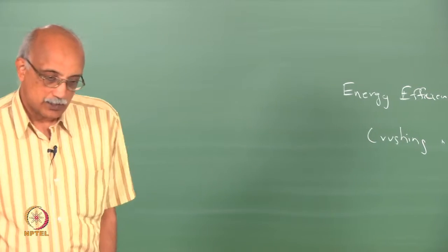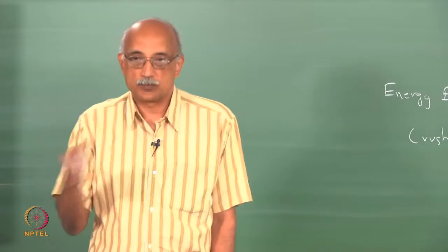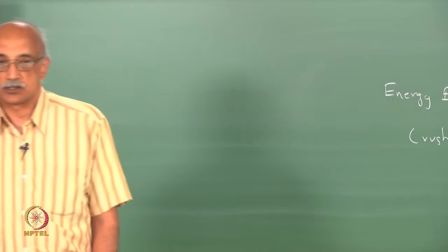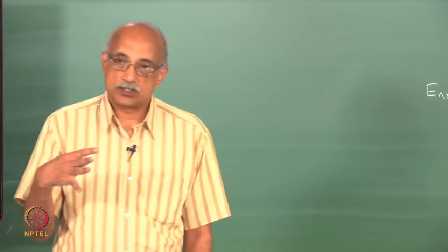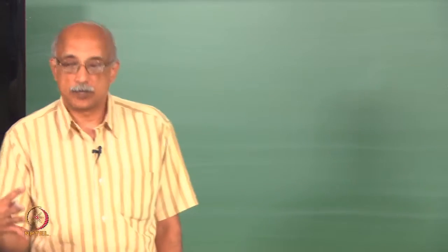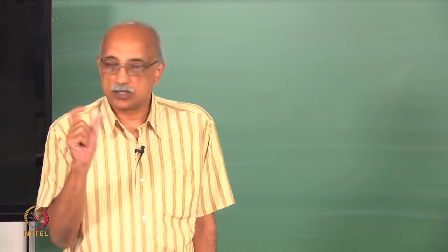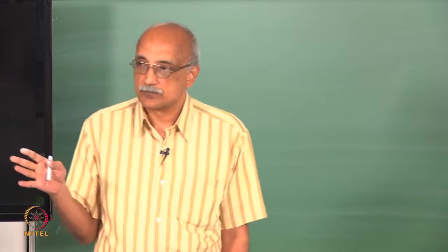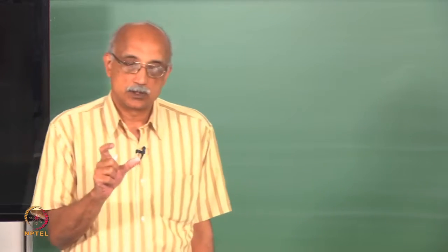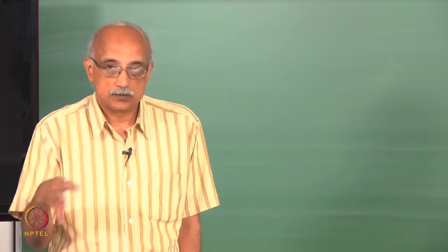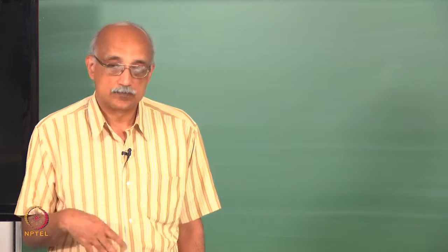Why is surface energy created? You have to look at the process by which fragmentation happens. When you supply energy to break down a material, what happens? First, the particle actually gets distorted. It does not fragment right away. It gets distorted, strain gets built in, or stress.